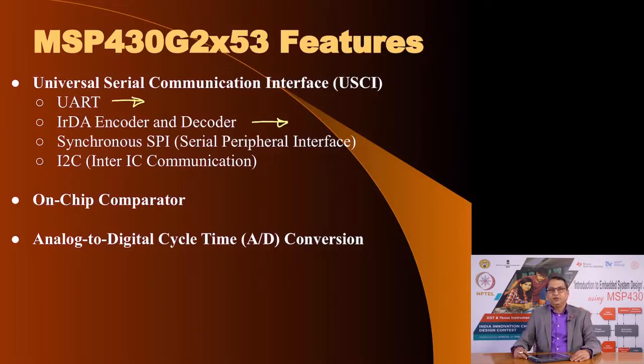It could be used for serial peripheral interface, what is called the SPI bus, and if you remember from those discussions, SPI and I2C, that is inter IC communication, were classified as intra device communication, that is within your gadget, that embedded system that you are building. If you want the microcontroller to communicate with an external IC which had this or this protocol, you could use the built-in communication capability of MSP430 to communicate with devices within the system.